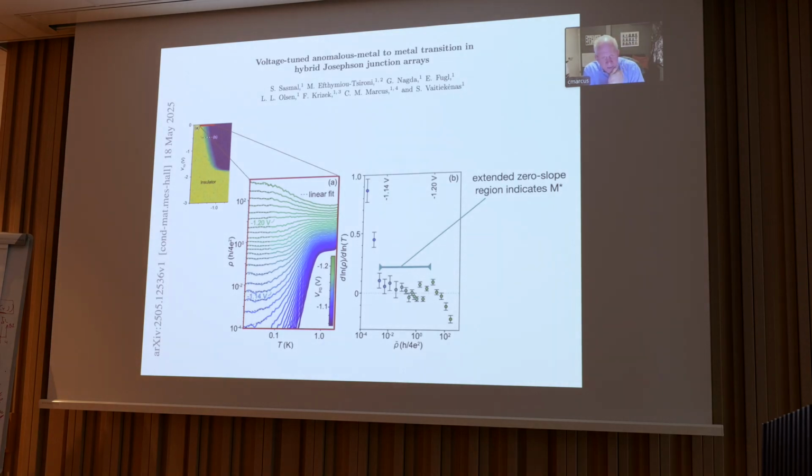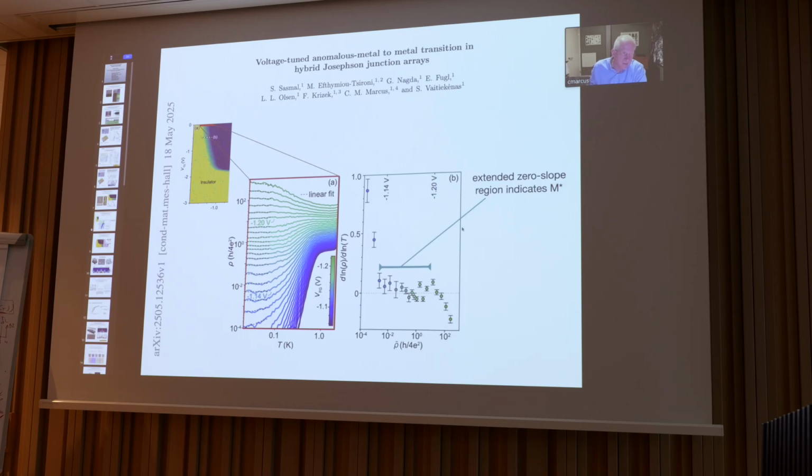We have a slightly more sophisticated way of deducing it now, which is to examine whether or not this low temperature curve really saturates, and doing that by fitting a slope to this log-log scale. And so if I fit a slope to each of these lines, I can plot that slope as a function of the gate voltage, in this case the gate that controls this horizontal axis, which is the frame gate. And I can see that on one side I have a superconducting phase, that is, the slope is positive. As the temperature goes down, the slope goes down.